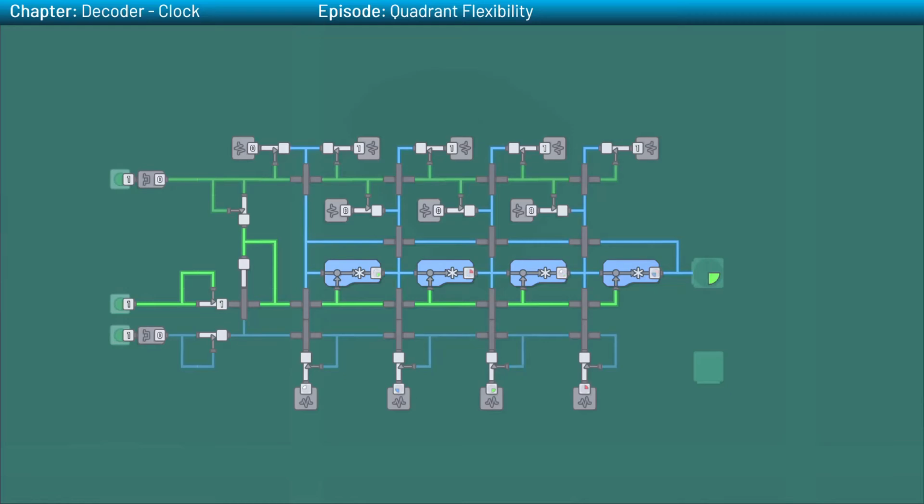Well, if it has fewer, for example 3, then I want the cycle to consist of 3 ticks instead of 4. And if we just load up 3 signals instead of 4 in this module the way it currently is, then unfortunately that won't affect the cycle time. Have a look at this. If we take away this second quadrant, we reset the module, and then we load up the values again, like so, and now we start cycling, then you see that we have an interruption.